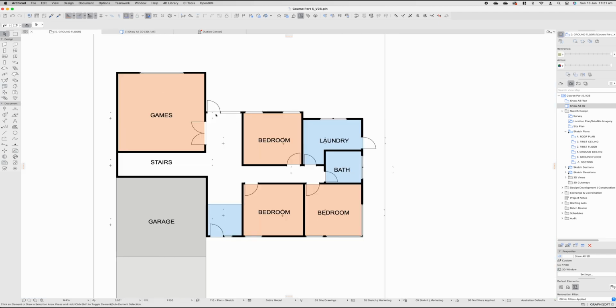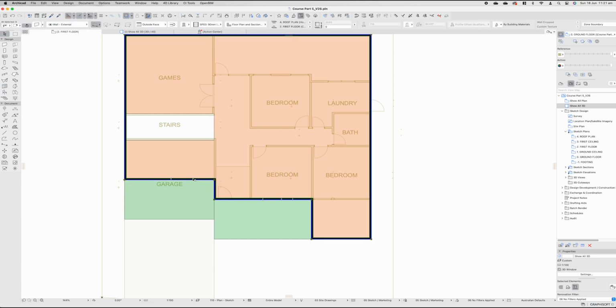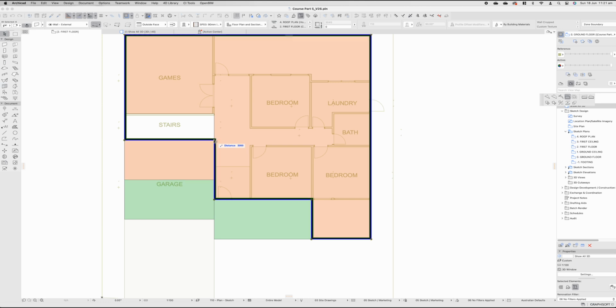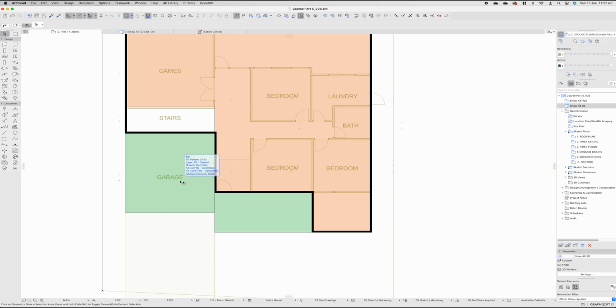So let's jump back to our ground floor plan, Command up to jump to our top floor. What I actually want to do is drag this back into our staircase because I don't want that there. So I'm going to select all of these walls, Option G to ungroup, select my blue line, go to my offset tool, and then drag that approximately back there. I can then reduce that section a lot bigger and increase the size of this overall space. You can actually fit something nice and reasonable on this side now, whereas previously you couldn't.